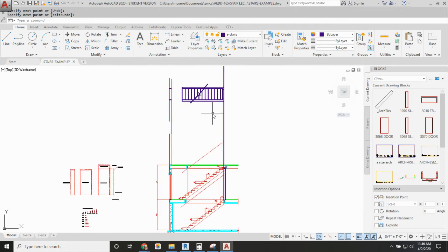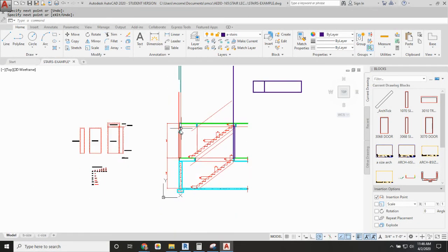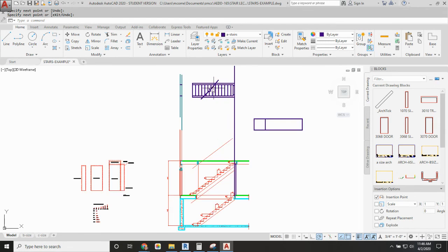So when you're designing a set of stairs to begin with, you can come up with approximates and say, all right, I know that I'm going to be doing a straight set of stairs, so I'm going to need 13 feet by 3 feet of space. That includes your landing. So if we put the 3-foot landing in here, there's the landing, and then there's the opening for the set of stairs that you'd need for clear space on that level. On the second floor, you'd have the same thing. You'd need a landing, but on the opposite side, plus the 12 inches. So this is a good way to start, just to ballpark where something's going to be. But once you've actually done a stair section, that's what's really going to inform you of where those walls are going to be on that plan view.